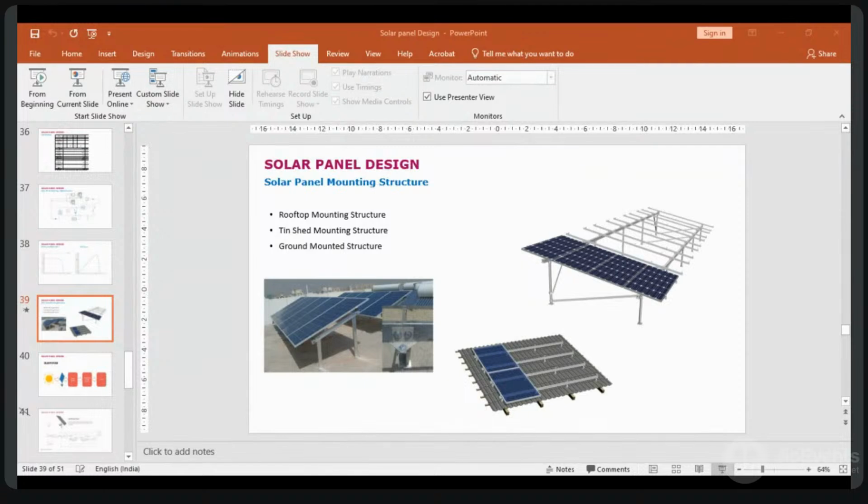And we also have the lightning arrestor. In order to protect from lightning, we even need to do the earth for the lightning electrode. So, already told, one is for the inverter AC, we need to do earthing, and also for the PV module, which is DC, we need to do the earthing. So we need earthing compound, already told.